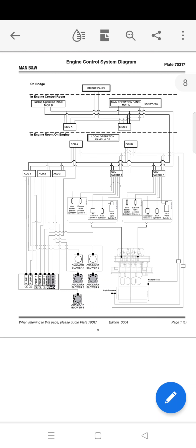Now ECU. The ECUs control the pressure of the hydraulic power supply system and the electrical startup of the pumps using the pressure set point given by the ECUs as a reference. Furthermore, the start and stop of the auxiliary blowers are controlled according to the scavenge air pressure. The control of the auxiliary equipment on the engine is normally divided among the ECUs so that in the event of a failure of one unit, there is sufficient redundancy to permit continuous operation of the engine.